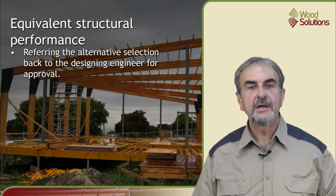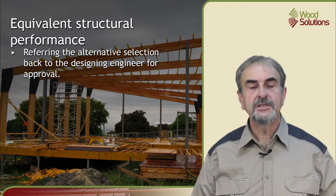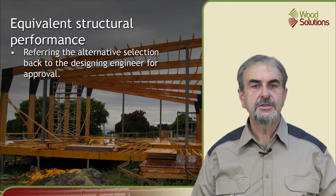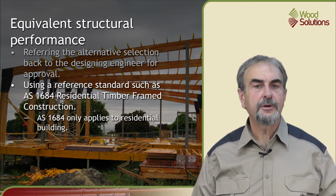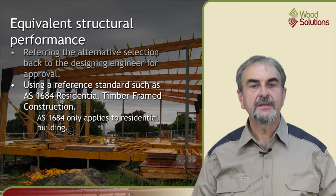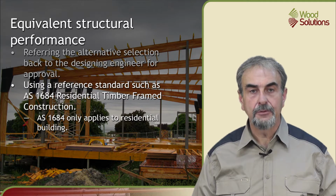There are 3 common ways of determining equivalent structural performance. The first is referring the alternative product back to the designing engineer. They then have to approve that the alternative product is suitable. The next is using a standard such as AS 1684 residential timber frame construction to confirm that the alternative product satisfies the application's requirement. However, remember that the AS 1684 only applies to residential buildings and it's no use for a commercial building or public buildings.